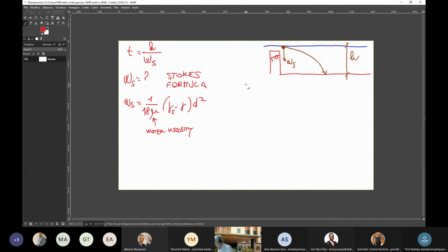And therefore, what is the length of the sand trap then? I said that the particle has to have enough time to settle down. So in order to settle down, it takes a time t. So the length of the sand trap is just the product of the velocity of flow times t. T is this one, and v is the velocity of flow.